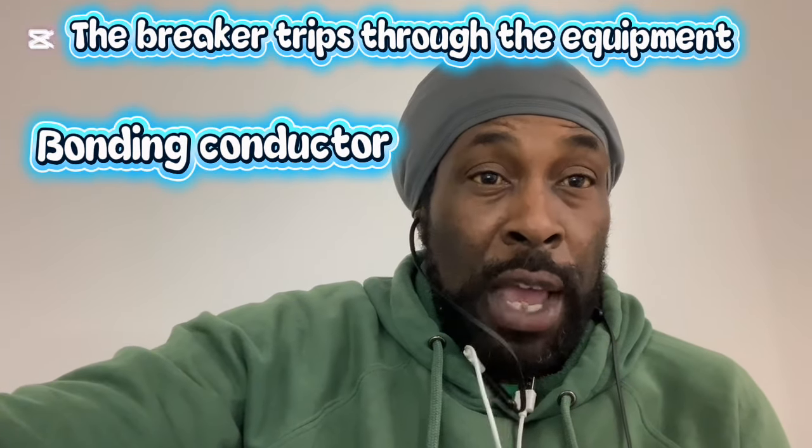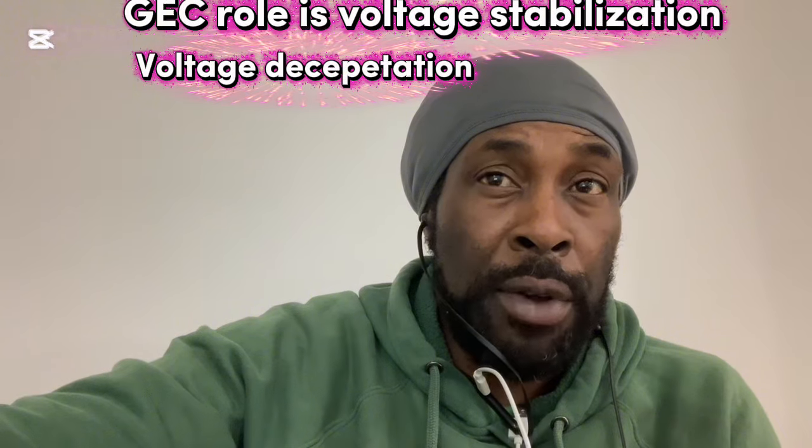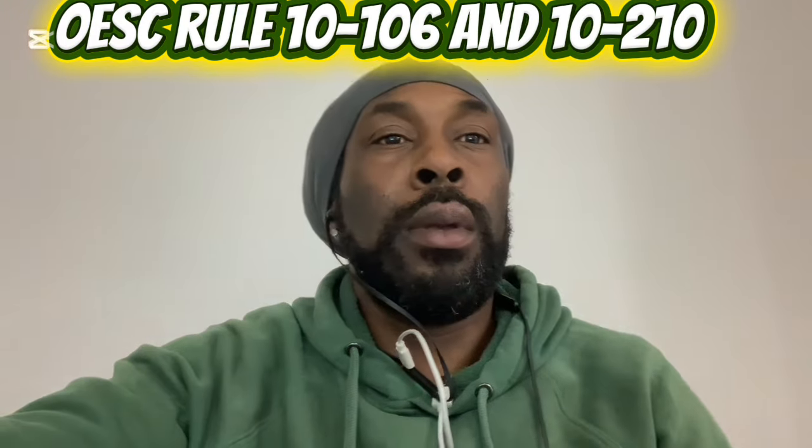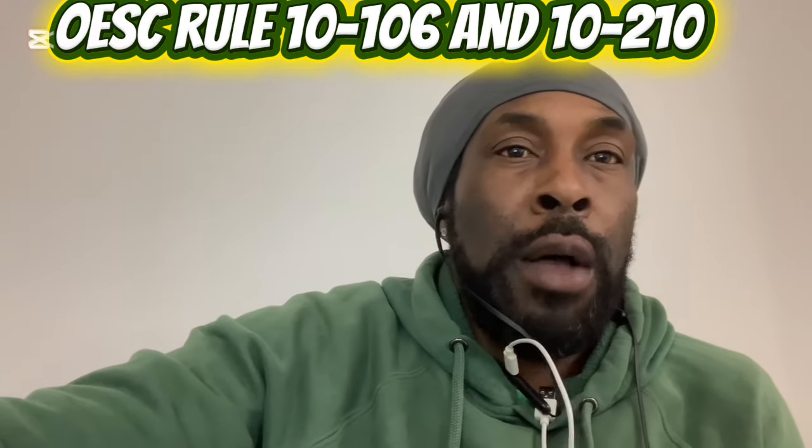The GEC role is voltage stabilization, surge dissipation, earth reference, that's it. OESC reference Rule 10-106, 10-210.